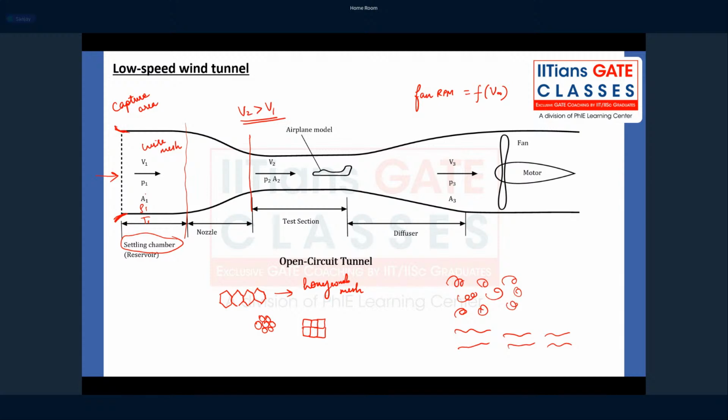Okay. In wind tunnel terminology, sometimes this nozzle is known as effuser. So diffuser is what diverges the flow, effuser is what converges the flow. So what this nozzle is going to do, it is going to increase the velocity. So it is going to expand the flow. Once the flow is at the exit of the nozzle, the flow velocity is very high. Not very high, it is high enough to achieve the flow conditions that you want.